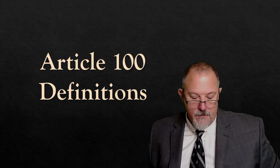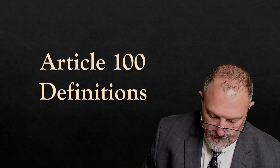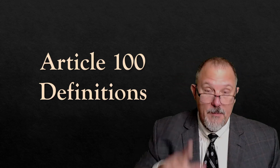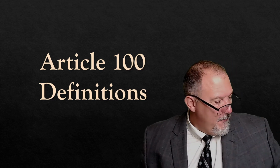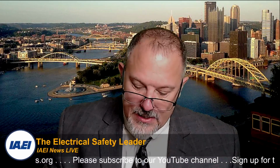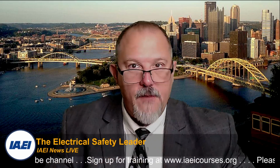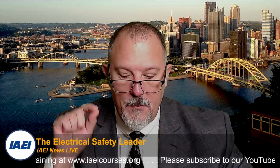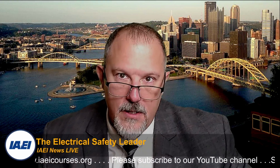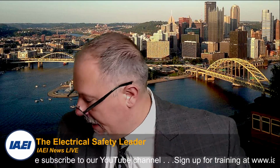Now, there are 5 little subdivisions. I don't know what you call these. We can't call them first level subdivisions. They're like definitions in a definition, which is kind of odd, but I believe we're addressing that. Time will tell. You've got to check out the 2023 code cycle. So let's take a look at what's inside the definition of a circuit breaker. We have adjustable as applied to circuit breakers. So you can have an adjustable circuit breaker. And what that's telling us is that a circuit breaker can be set to trip at various values of current. Not all circuit breakers, but a circuit breaker can be set. How do we do that? How do we get that done?